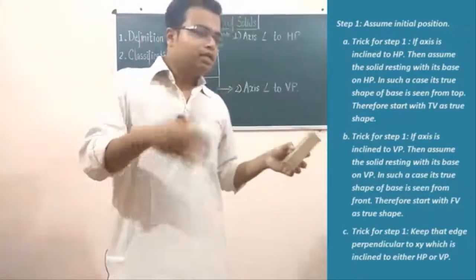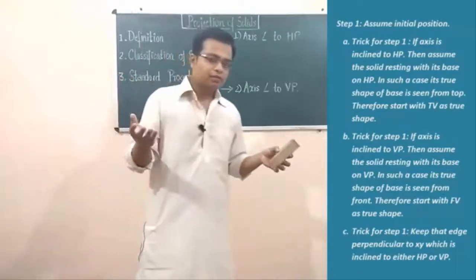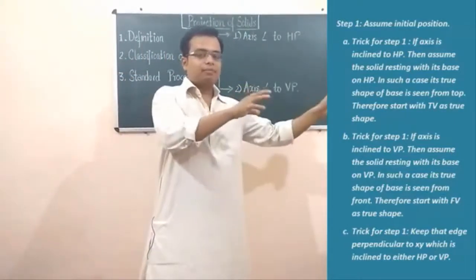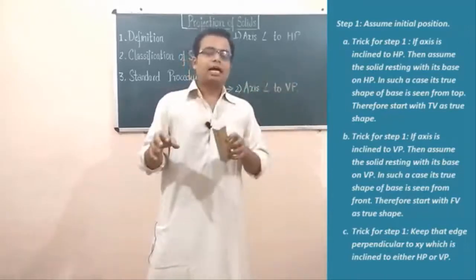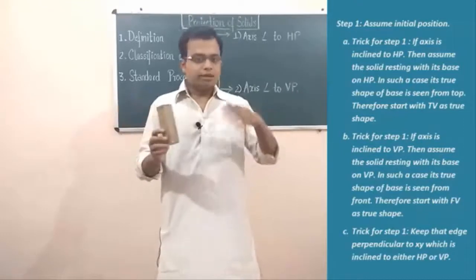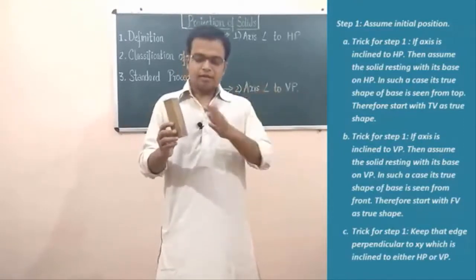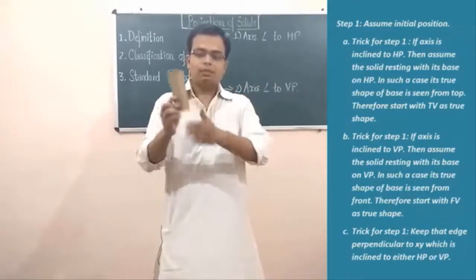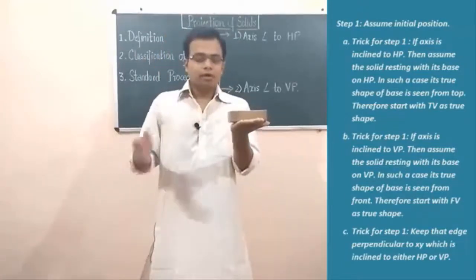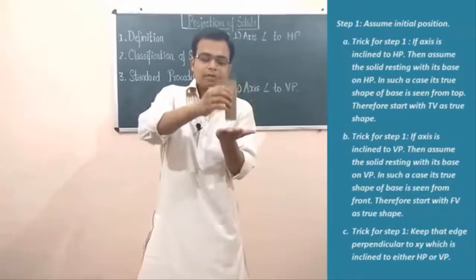And let's say in step number 3 we have to go for edge inclination. Always remember, whichever edge is inclined in step number 3, it initially has to be kept perpendicular to XY. That's it. Now there are certain cases that you have to deal with in which you'll find that a face is resting on the HP. Then what are you going to do? In such a case, initially you have to keep it standing.